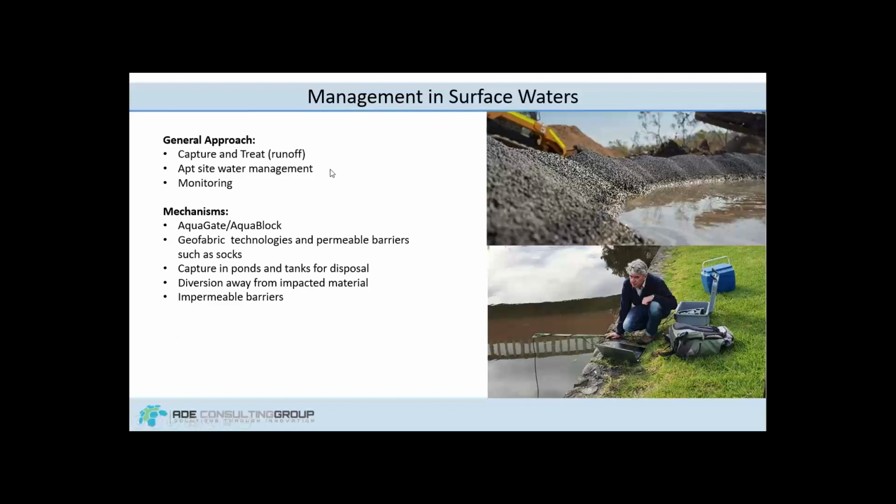Surface water is a similar case. This is a management approach rather than a remediation approach. Well, it could be argued in the case of groundwater, pumping out plumes and removing them is a remediation approach, and it technically is. If the source hasn't been addressed, we'll be there for a while pumping out water. So a typical approach is capture and treat, on-site water management and monitoring. So site water management can mean diverting water away from areas that are known to have PFAS impacts and putting in place management practices that reduce the generation of PFAS impacted water, such as covering stockpiles, etc.